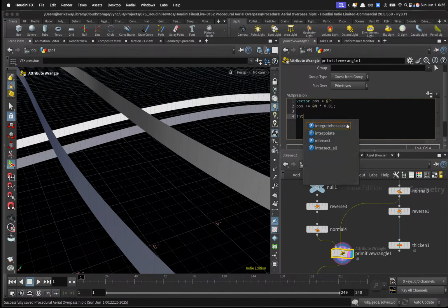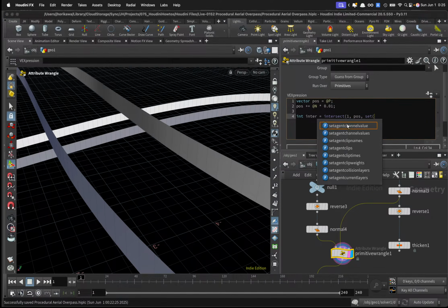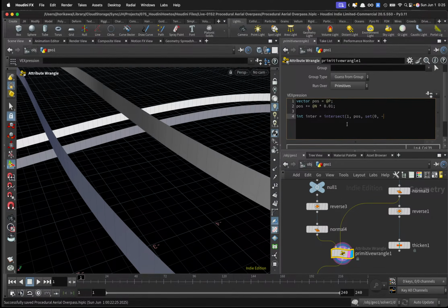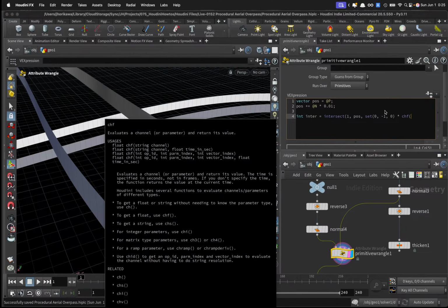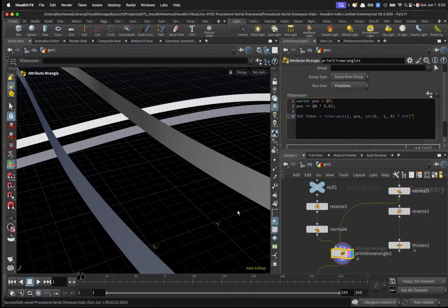Then try to create an intersection analysis with the second input, which is the floor face of the road, in the negative direction of the road. But you also want to specify the height of the intersection ray, which should be close to the fence height, because you're using the center point position of the fence.